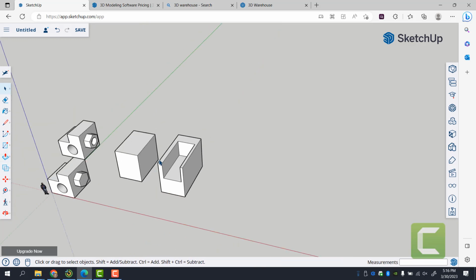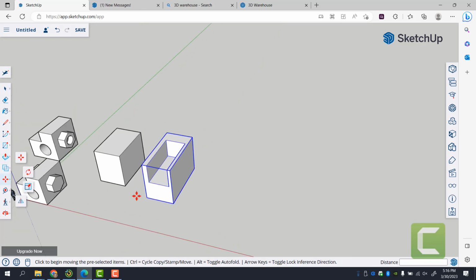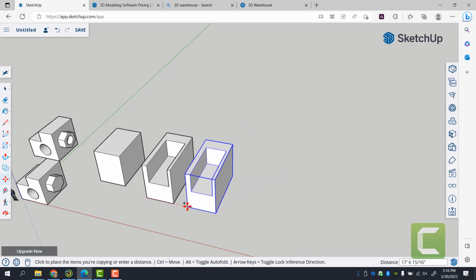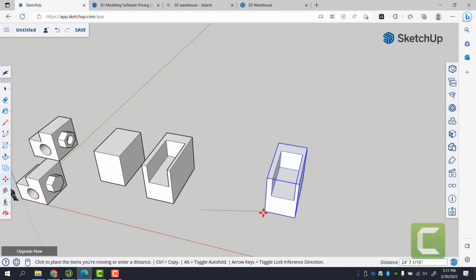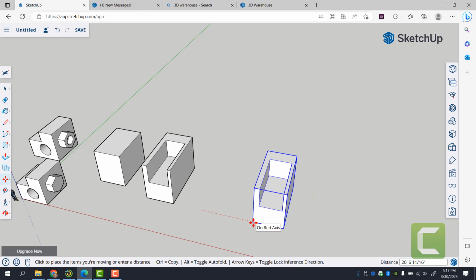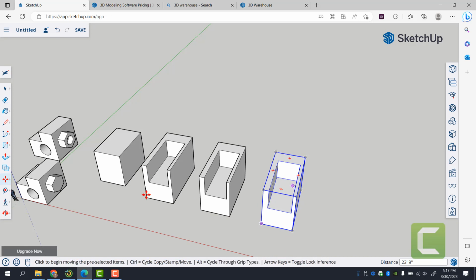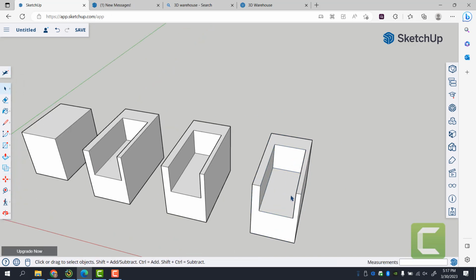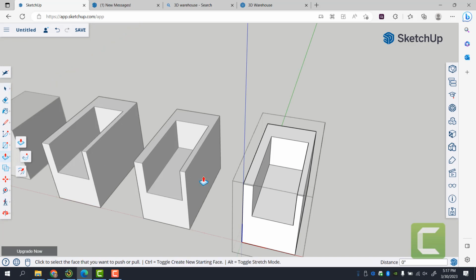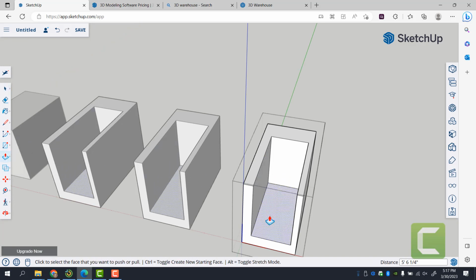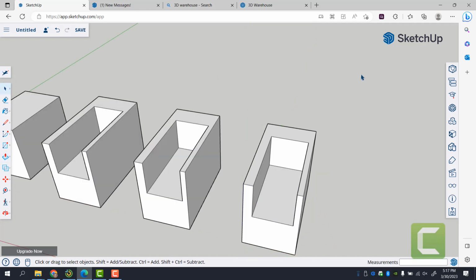So once I have this chair drawn, I can simply copy it around by using move copy. Again, I select the move tool, hit the control key once, and I can move copy. If I hit the move tool and I do not use the control key, it simply is moving that object. Control makes another copy. So now I have these three chairs. Now, let's say the height of these chairs changes, or we have to add a cushion to the back. I simply click on one of the components, and as I alter this one component, it will alter all the components that are linked to it. Again, this is the chair component.